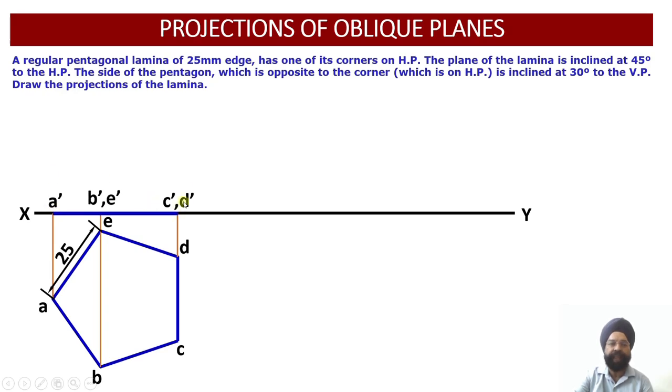So we have to incline this lamina by picking up this corner of the edge view. That is, we have to incline it this way so that it will be resting on the horizontal plane on one of its corners. Just see, we are going to draw one projector line through this, and this angle of inclination will be 45 degree.